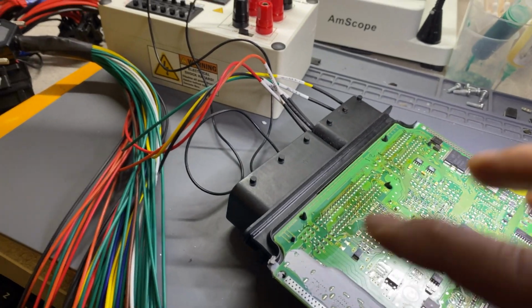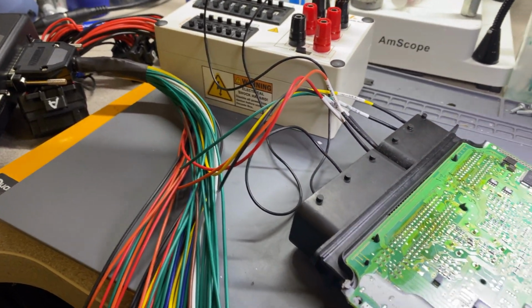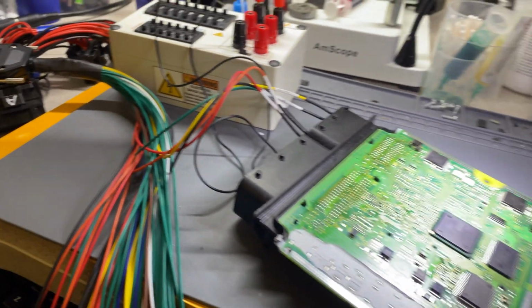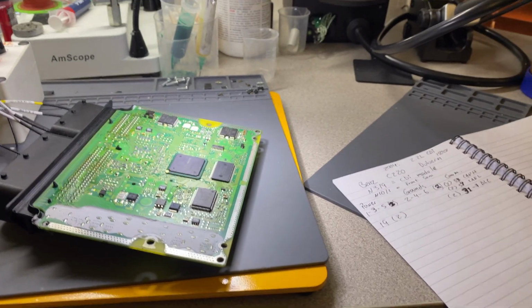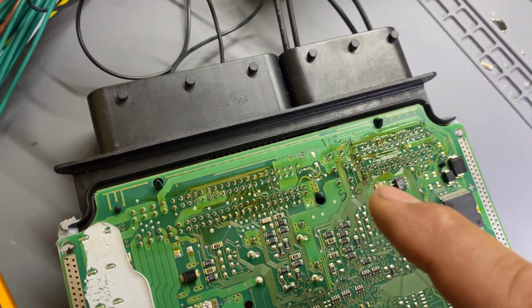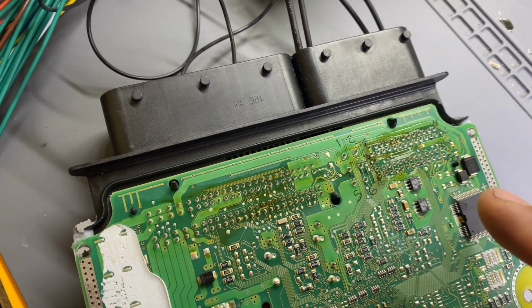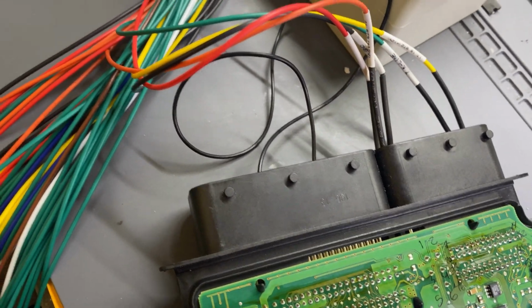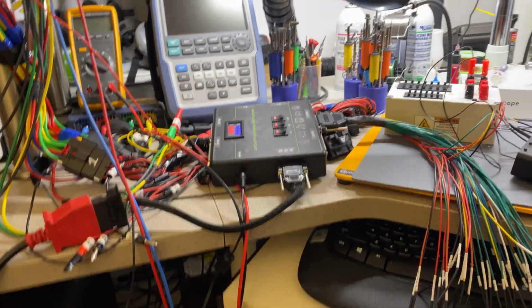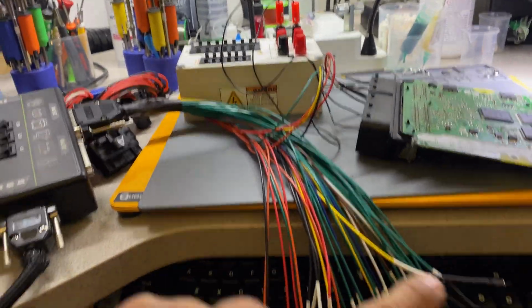These computers use 2 connectors. The big one with like, I don't know how many pins, is number 1, and the one with 58 pins is connector 2. So I have all that set up. I also put here the CAN high and low, just because I also marked, let me move this microscope out of the way, I marked the connector 2 here with just a pen to know which are pins 53 and 54 for the CAN line, and also the K line to check that communication in case I wasn't able to talk to it. So I provided the powers and grounds with these.